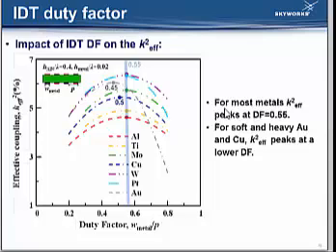We can see, again, there is a top value because of the balance between reflection and the non-piezo loading. For most metals, including tungsten, platinum, moly, and titanium, the top value is when the duty factor equals 0.55. For gold and copper, the effective coupling reaches maximum at 0.45 and 0.5.